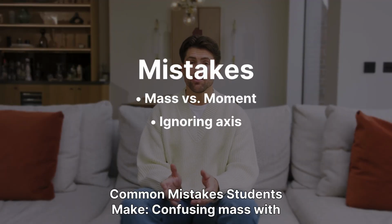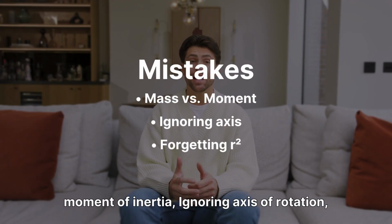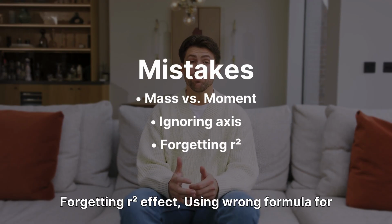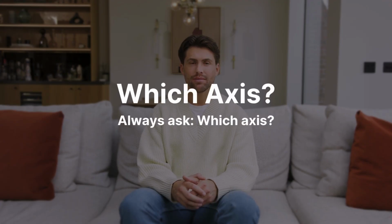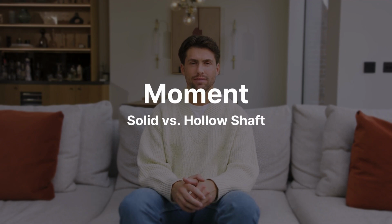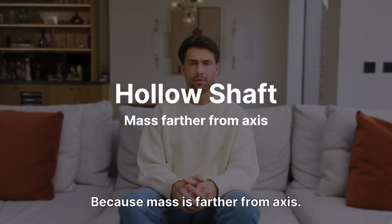Common mistakes students make: confusing mass with moment of inertia, ignoring axis of rotation, forgetting the r squared effect, using wrong formula for body shape. Always ask about which axis. Which has higher moment of inertia? Solid shaft or hollow shaft? Answer: hollow shaft. Why? Because mass is farther from the axis.